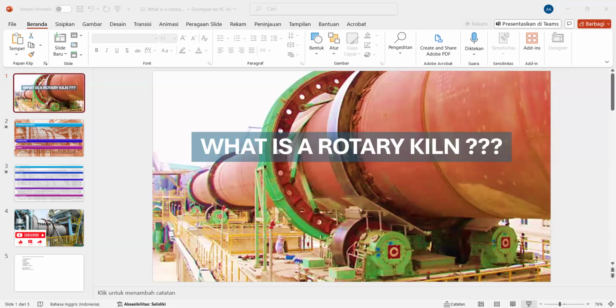The design requires some tolerance, as the tyre must fit the shell snugly but also allow thermal movement. The tyres ride on pairs of steel rollers, also machined to a smooth surface, and these are spaced about one and a half kiln diameters apart.